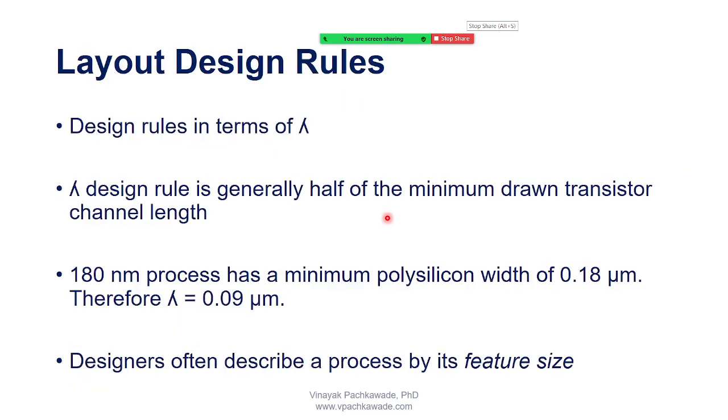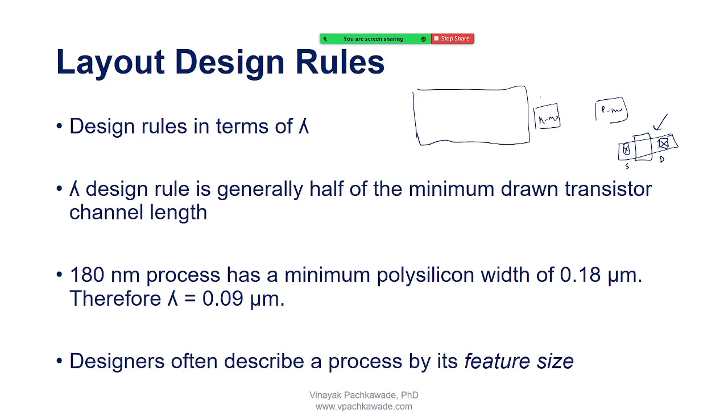So let's talk about layout design rules. I go to the library and, as I said, I will have access to ready cells, NMOS and then PMOS again. These cells are like the gate, for instance, this is source and drain. So you'll pick up these transistors, whether NMOS or PMOS, and then you will have a schematic screen, the layout diagram screen on your tool, right?